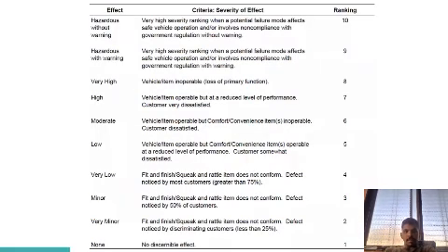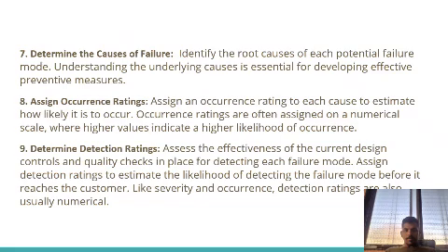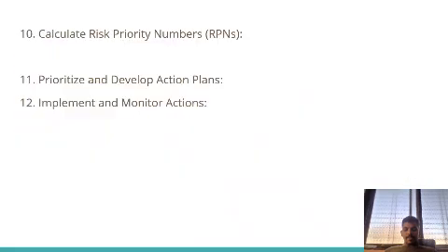There are some effects criteria for the severity ranking. Determine the cause of failure, assign occurrence rating, determine the detection rating, calculate the risk priority number, prioritize and develop action plans, implement and monitor actions.